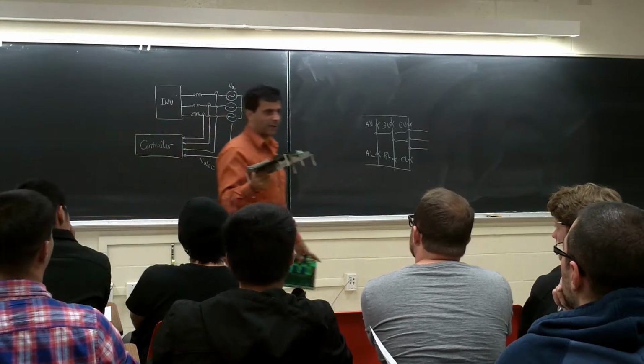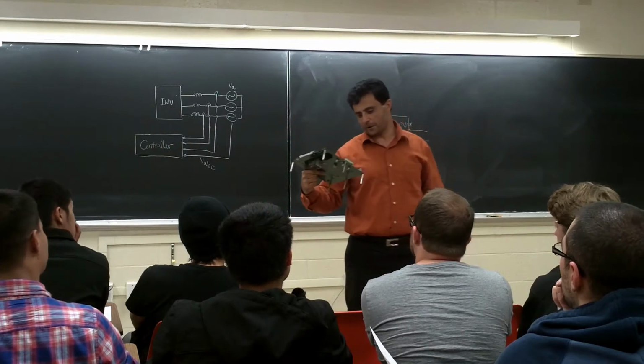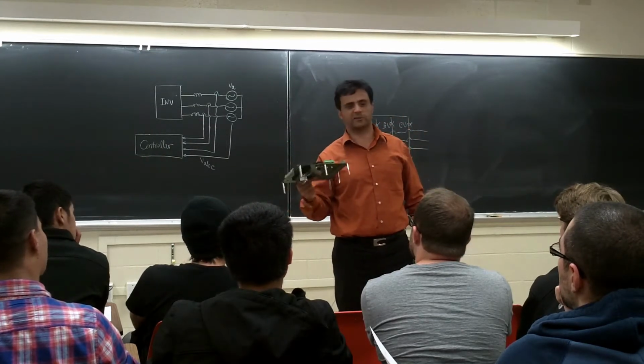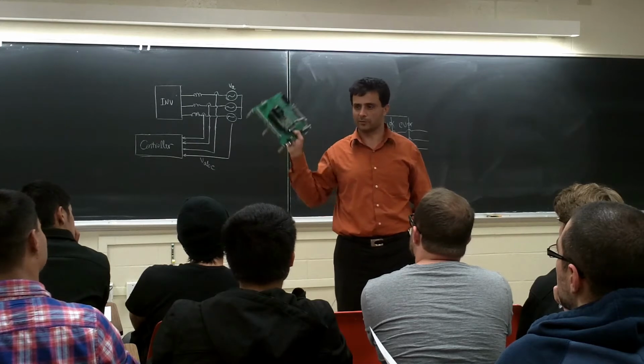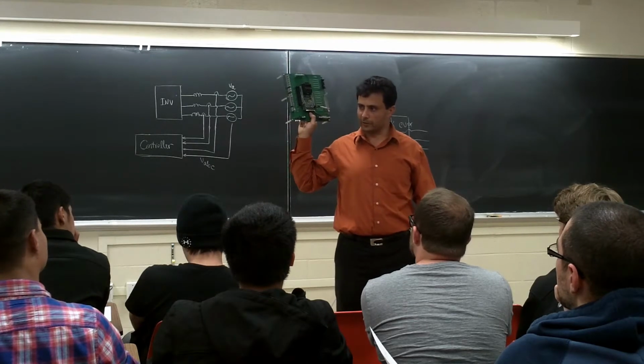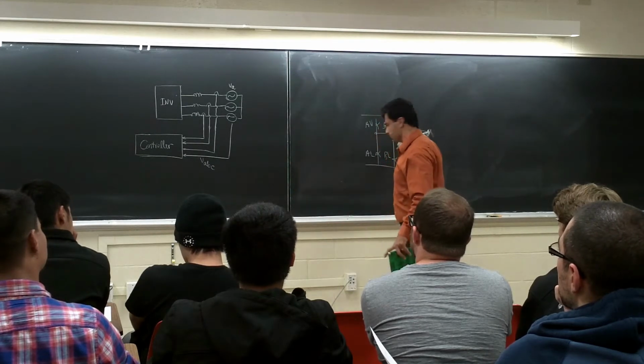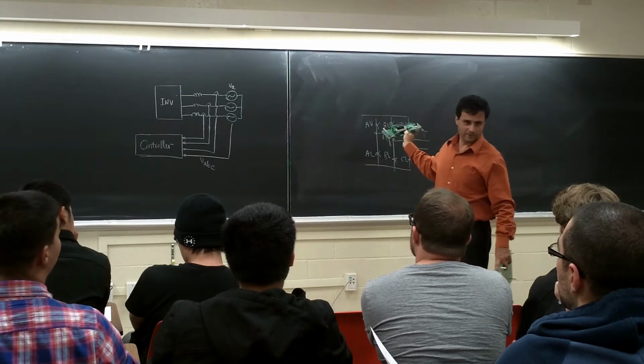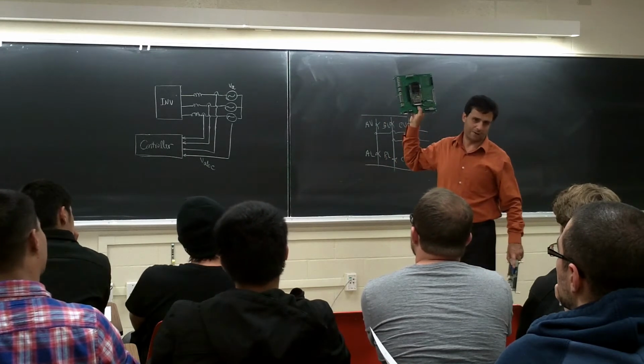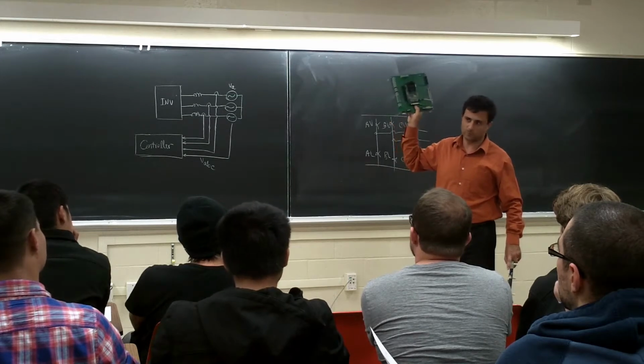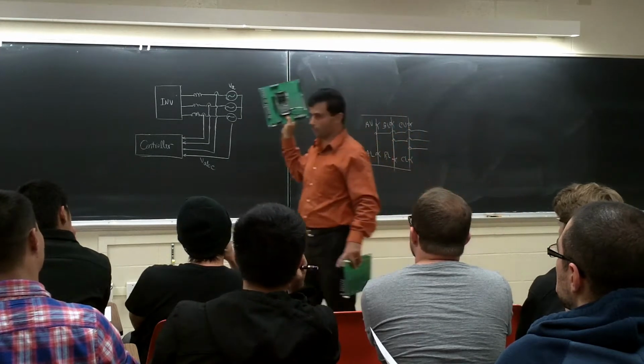These are for the inverter, the 3-phase inverter. And there are 4 more PWM channels. These are like independent PWM channels. With this one, you can drive 2 of these inverters at the same time. This is designed for motor drives, which have a back-to-back inverter. So with one DSP, you can drive both.